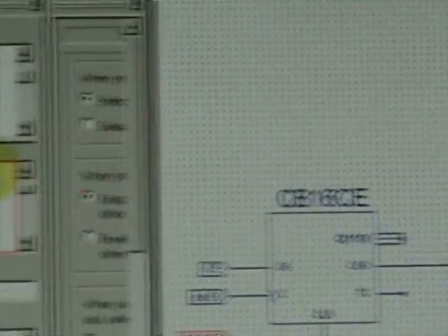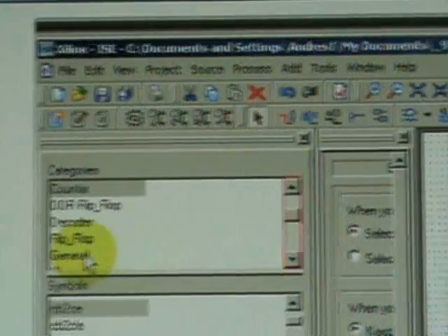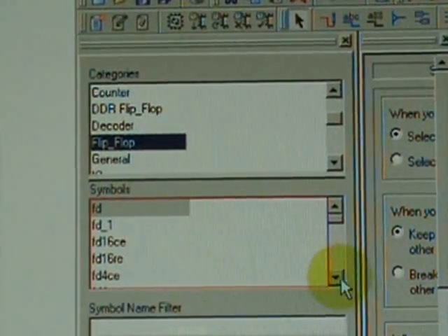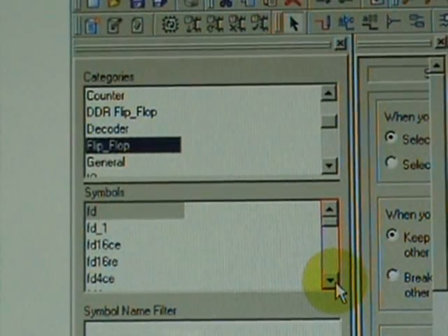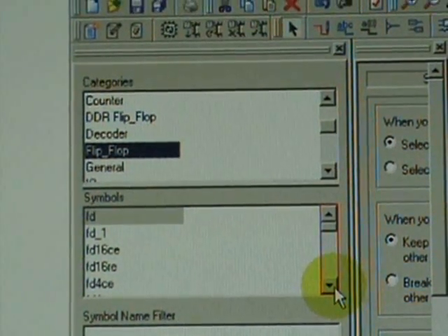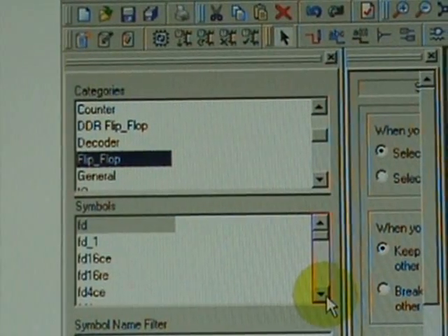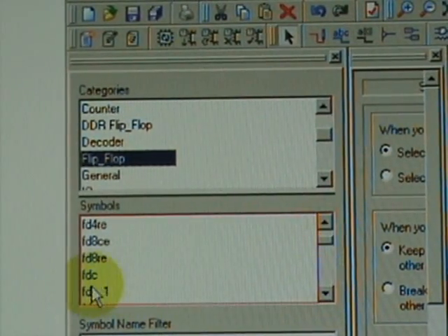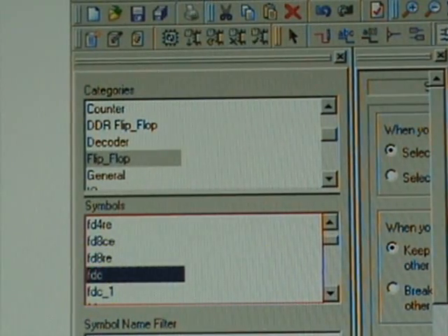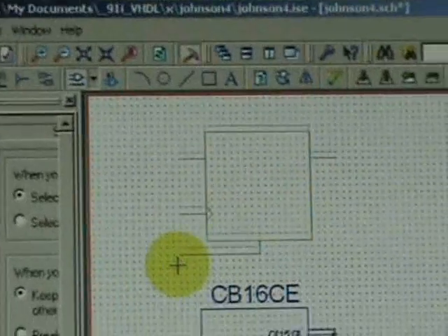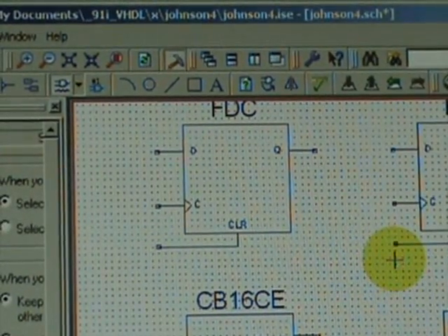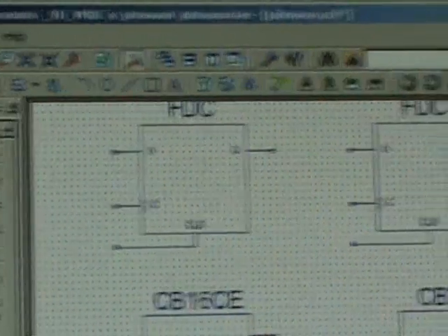So the next thing to do is to connect a handful of data flip-flops. That is, in flip-flop they call it F. If there is a clear input, then that is FDC. The FDC underscore is a negative edge data flip-flop, which we will not use.